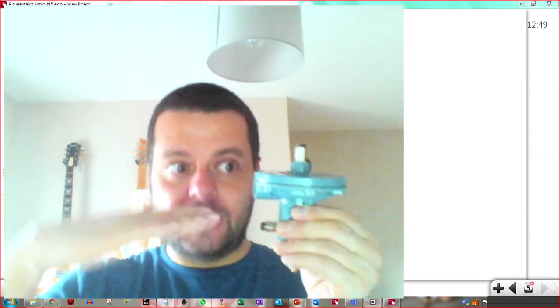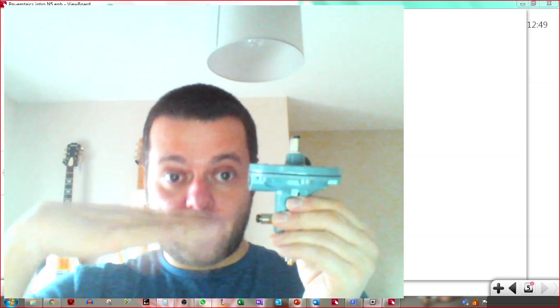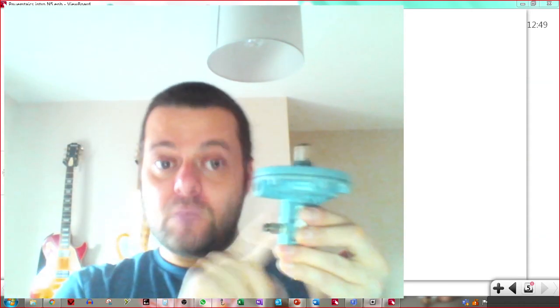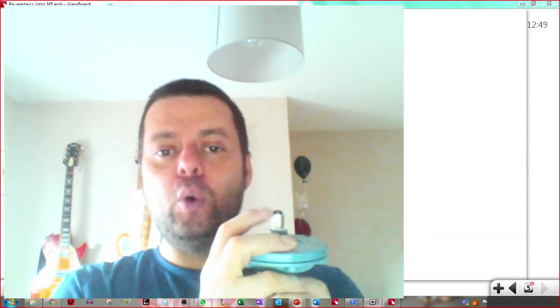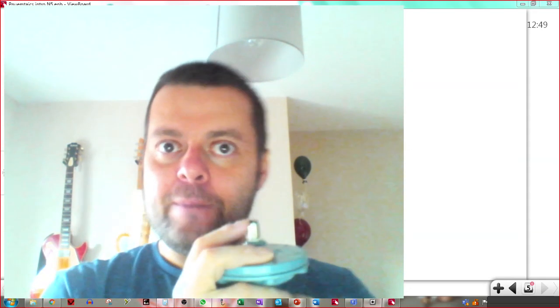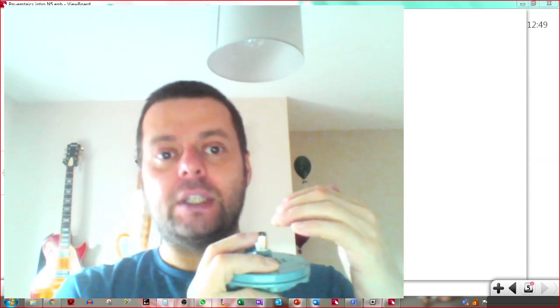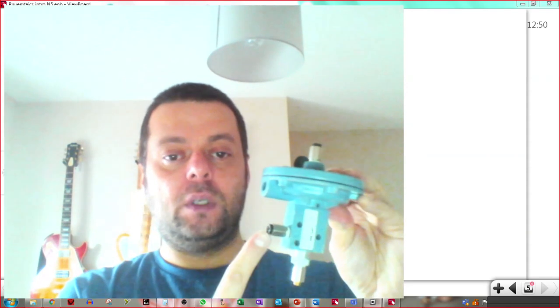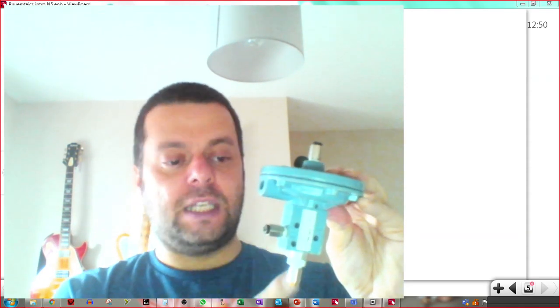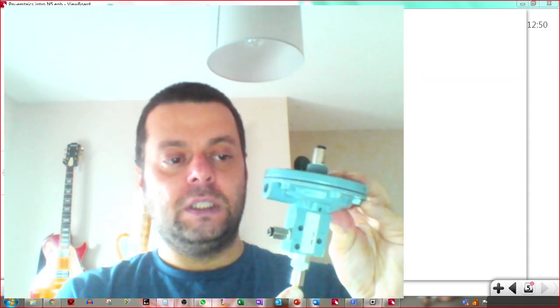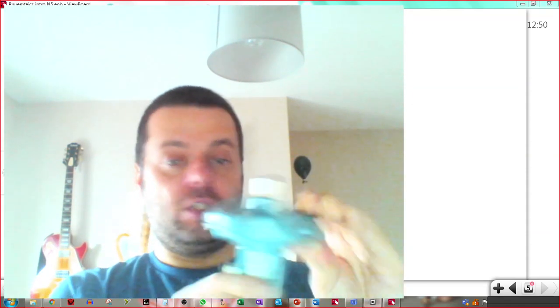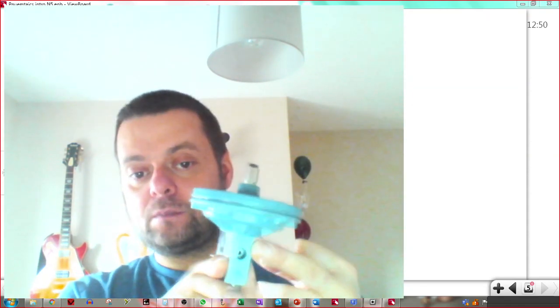Yeah, it'll start to inflate and a bit of rubber will start to push down. And we can use that physical deflection to change the 3-2 valve. So this port on the top is actually to give you an air pressure signal to the diaphragm. And then the ones on the bottom, you've got input and output. In this state, the input isn't connected to anything, and the output is connected to the exhaust, which is a hole on this side here.